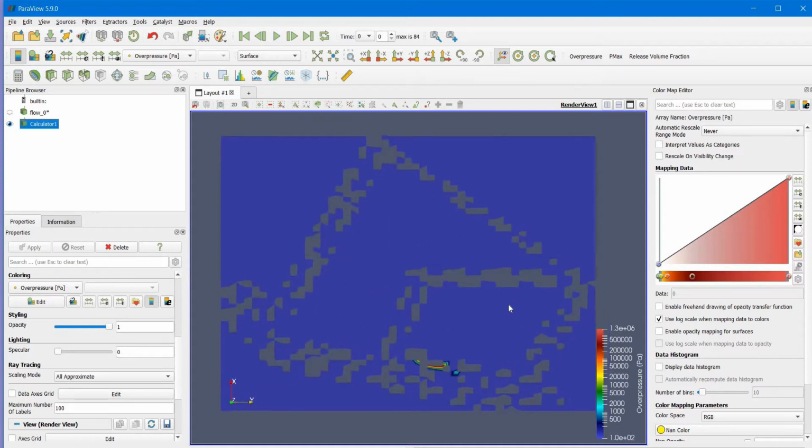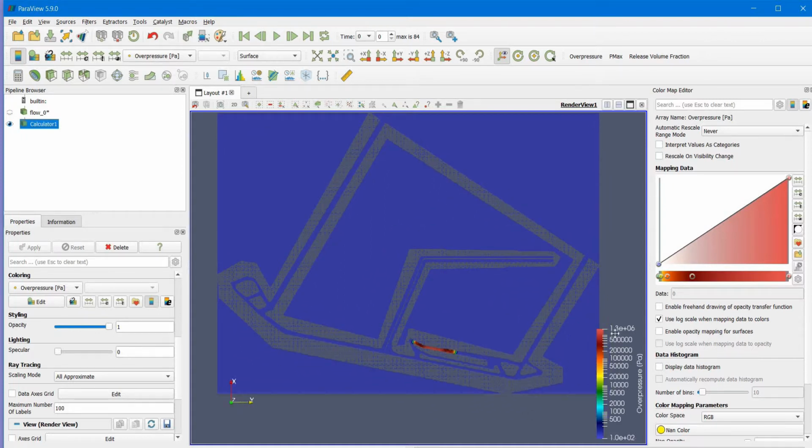You don't really care below that. So you can see the maximum pressure here is significantly higher than the 4 bar, or 5 bar, that we had. We now have 1.3 megapascals of pressure, and that's typical because dust explosions can be very powerful indeed.